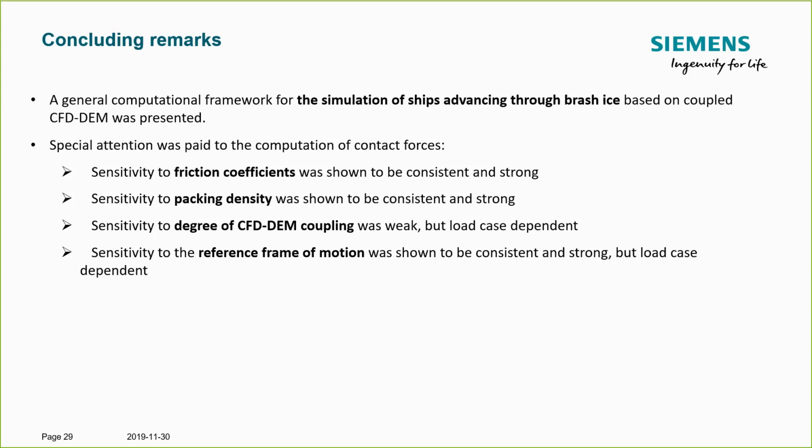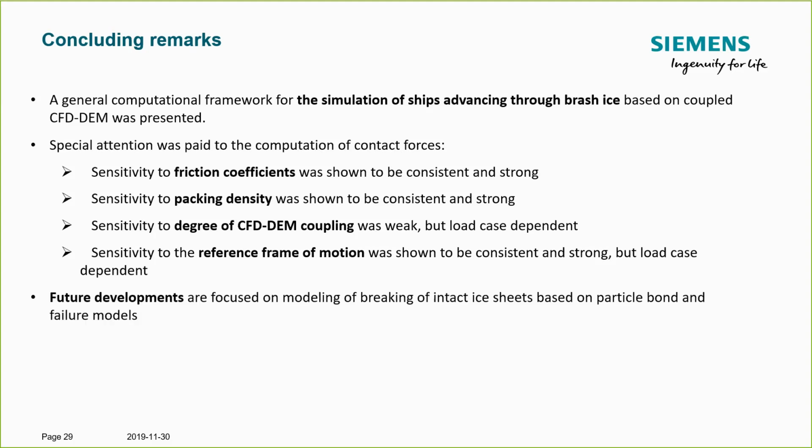Higher packing density, larger particles, the more likely you have to run two-way coupling. The sensitivity to the reference frame of motion was shown to be consistent and strong, but it's also load case dependent. Future developments on our side are focused on the modeling of breaking of impact ice sheets based on particle bond and failure models.